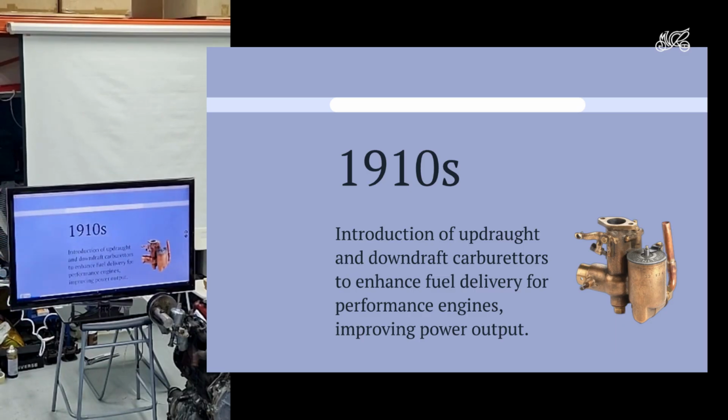So the Venturi effect is if you're sucking air through a pipe and the pipe has got a constriction in it, at that point, the air goes faster to get through the constriction. And when the air is moving faster, the pressure is lower. And so if you put a pipe in the side where that constriction is, it will suck whatever it is out of that pipe. So the basics of a carburetor is exploiting the Venturi effect.